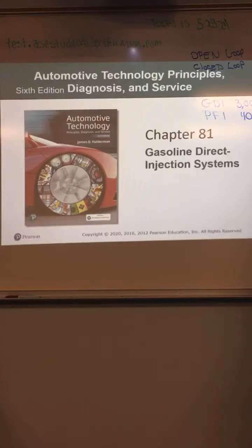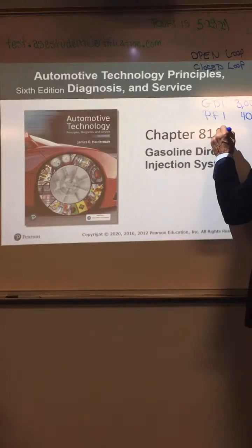Am I understanding that right? And for the GDI, it's varying the fuel pressure, okay. So the port is varying the injector pulse width on a port fuel injected engine, meaning how long the injector's open. Okay, the other thing is, a GDI system is going to have 2 fuel pumps, right?